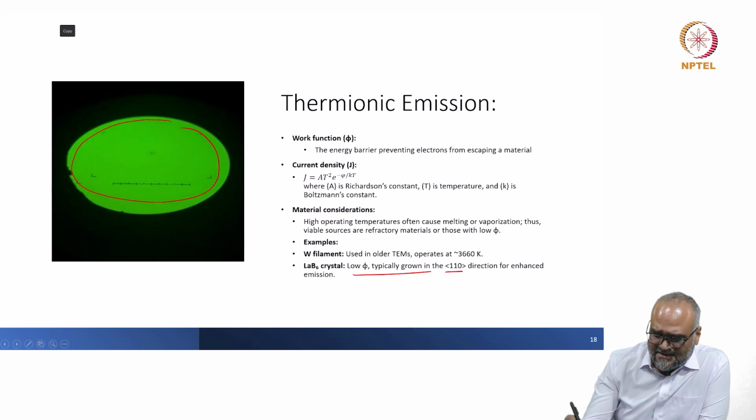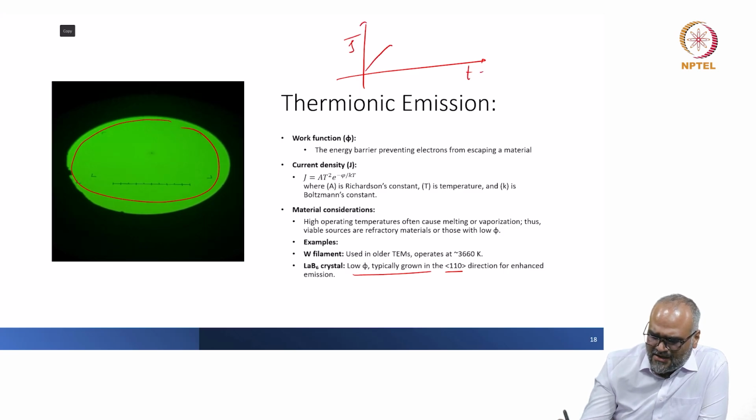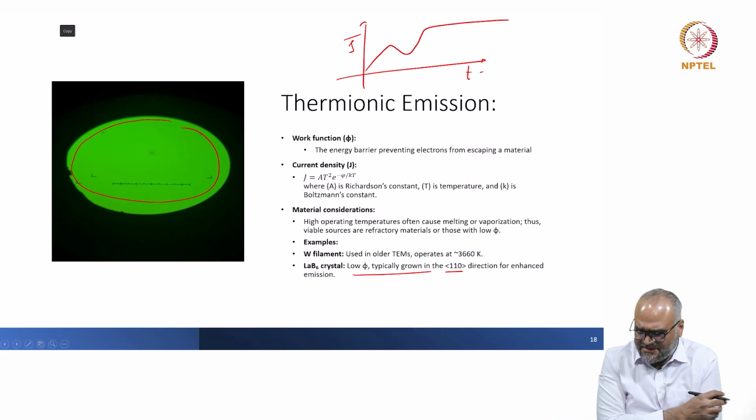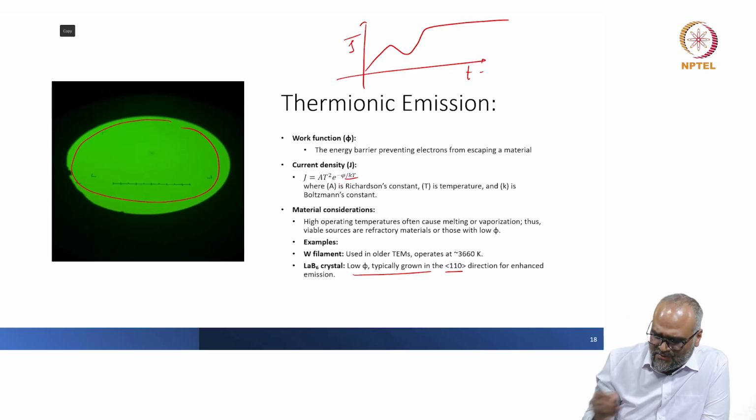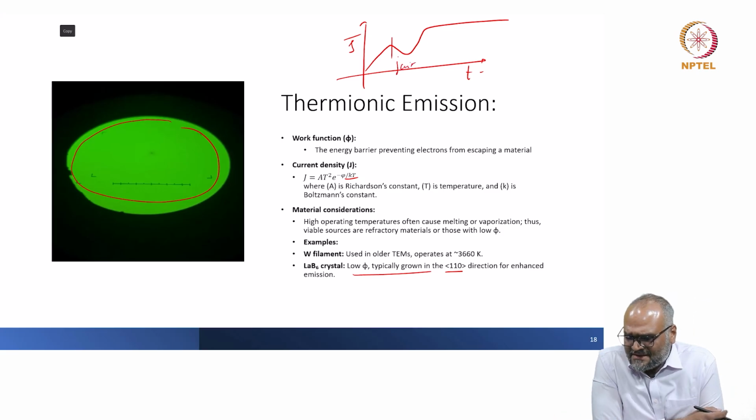If I now plot this current density as a function of time, I had the small jump and then I had the sustained emission. This was the graph that I showed you on the other screen as well some time ago when I defined this equation. I have to overcome this critical current density. That is because of the kind of shielding layer that is formed with all the electrons that are extracted right in front of the tip, and beyond this I have a sustained emission.